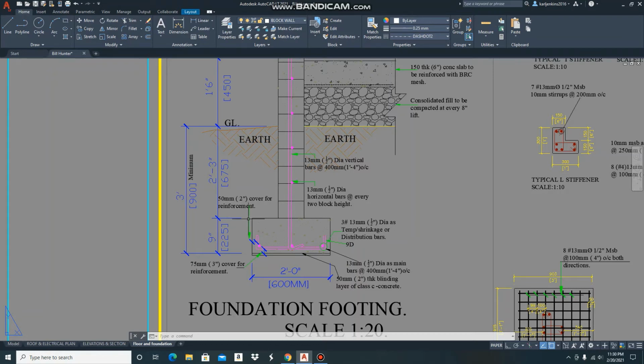Your thickness of your footing now is very, very critical also, because your thickness of your footing is to resist against what is called punching shear. Your thickness of your wall footing should be designed to resist the wall itself, due to its weight, from punching through the thickness of your wall footing.